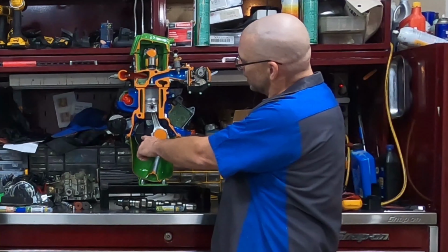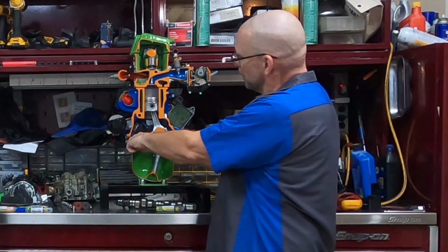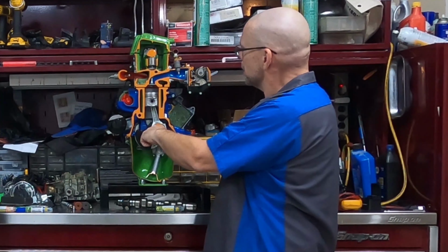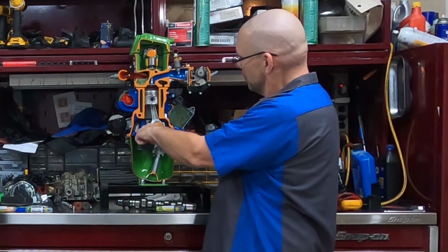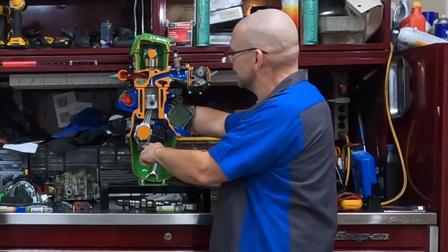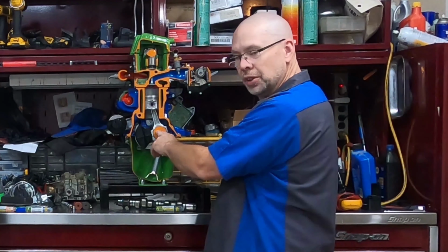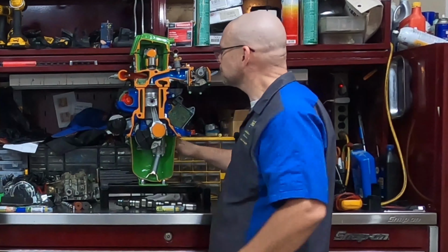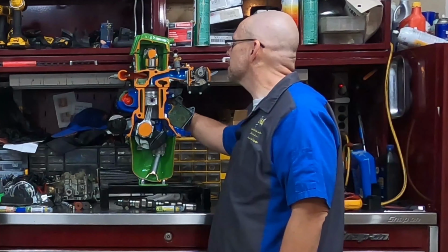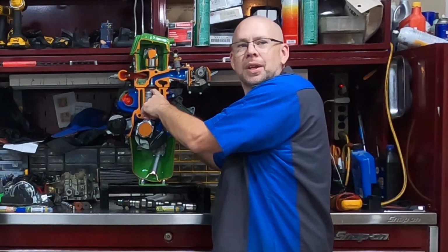And some of that is simple mechanics. As our crankshaft, right here we're at a 90-degree angle on the crankshaft to center of our cylinder line. Then as we come up, now we have a different mechanical leverage here. Same thing on the way down. So some of that is simply the way that this is designed. If they offset the rod, it's a little bit different because it changes this lever. Just remember, general rules, we want to fire it so that it is completely burned out by between 10 and 20 degrees after top dead center.